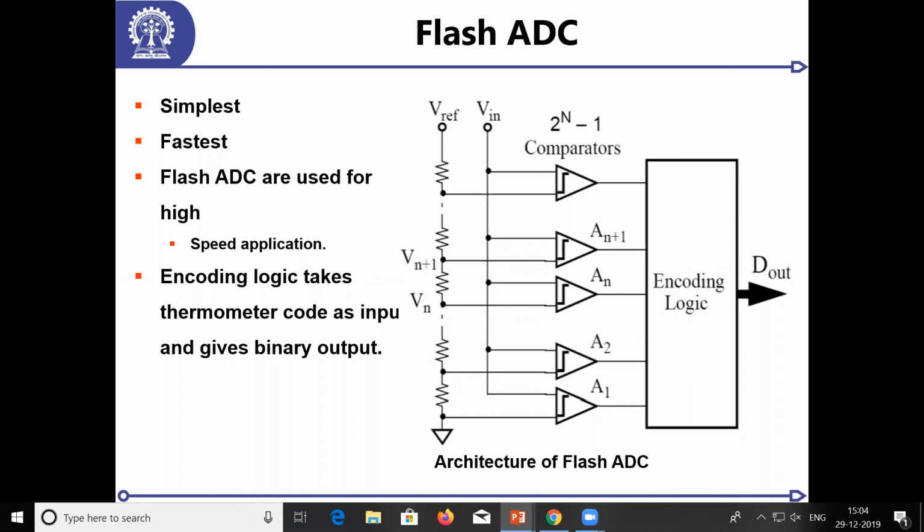Now, as I said, in nanometer CMOS, you have resistors that are not perfect. These are tiny resistors, right? And mismatches are large, so I have to estimate the mismatch between them. Similarly, these comparators are made of two transistors. They will have offset, they'll have mismatches. This will cause me some other error. So how do I estimate that? That estimation of the unknowns inside the circuit after the chip has come back is called calibration.